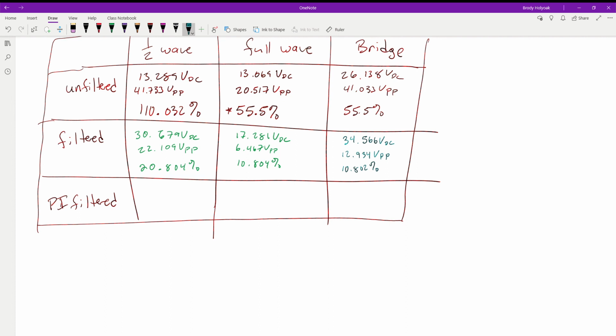we could just use a full wave because we don't need that extra voltage. Whatever voltage we don't use, which is what we're going to talk about in the next section with our pi filters, has to go somewhere. So we have another resistor, we call it a shunt resistor, that we shove everything we don't want onto. The more voltage we shove over there, the more power it has, and the more heat it's going to produce. The more heat it produces, the bigger the resistor has to be to handle it.